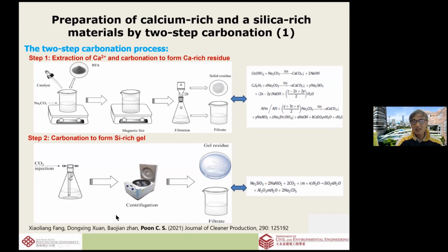So in the laboratory, this is the recycled fine powder. Mainly, this is cement powder, hydrated cement paste. Of course, there's some contaminant, but mainly recycled cement paste. So in the lab, we use cement paste as a simulated powder. We put it into a large beaker, and then we add water, and then add the sodium carbonate. Sodium carbonate is a source of carbonate.